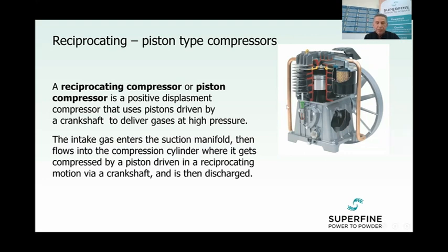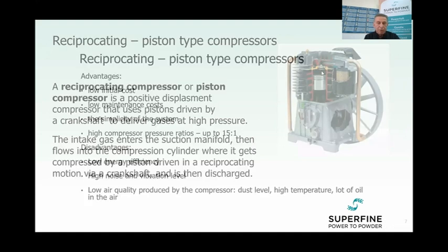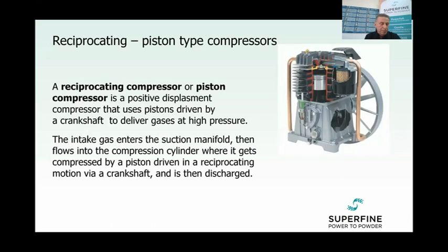The intake gas enters the suction manifold, then flows into the compression cylinder, where it gets compressed by a piston driving in a reciprocating motion via a crankshaft, and then is discharged. Applications include oil refineries, gas pipelines, chemical plants, natural gas processing plants, and air-conditioning and refrigeration plants.